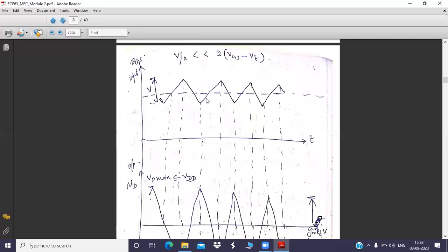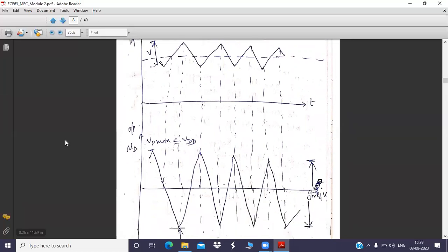So this is your input signal, which is very weak, very small amplitude, and while drawing the output, vd is your output. While drawing the output it should be enlarged and it should be 180 degrees out of phase. See how it is being done. This is going to negative, this is going to positive, so meanwhile it should go to negative. This line is going towards the negative side, but at the same time, when you track downwards, this is going towards positive. So this shows that this is inverting. This is 180 degrees out of phase with each other.